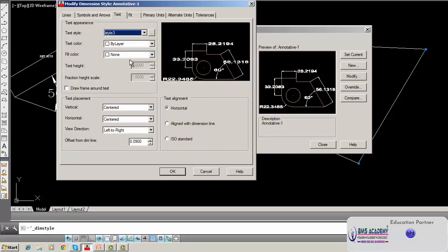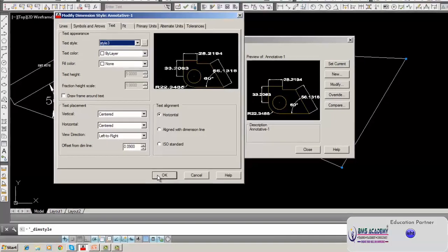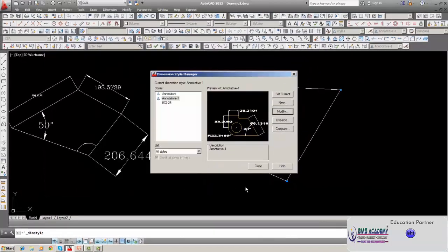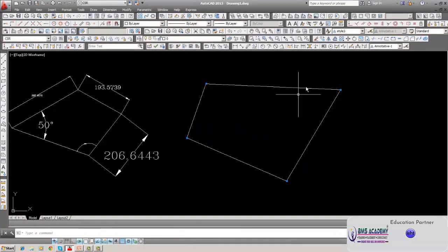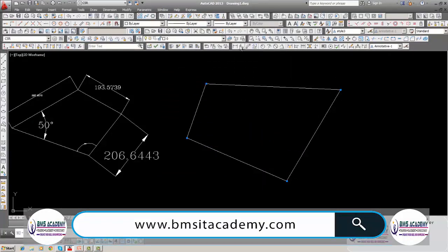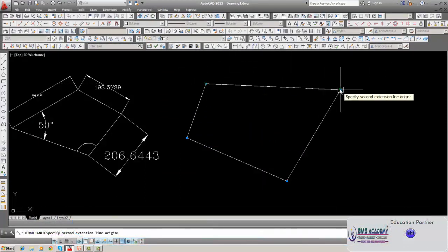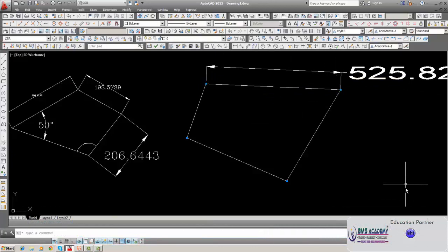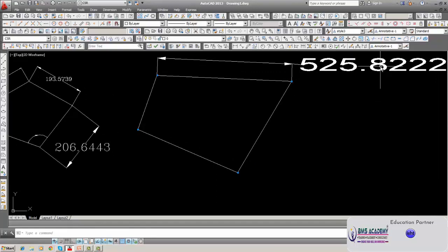Okay, now we get into proper channel. So here we have selected everything properly, and we click on this, and now this is the same, and you close it, and now you have selected annotative 1, and you may manage it. See, the font is different, and the height will be dependent upon what is set in relative scale, and that is 10 times.